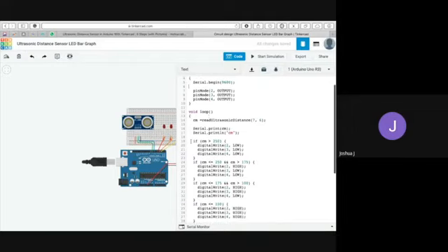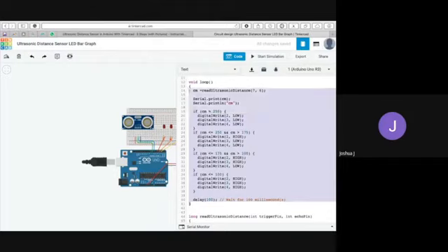And this is my main loop. In my main loop, I call a function. This is my own function that we write for our custom use, and here we read the value. When line statement 14 is executed, it will go to this function, and the function's statements will be executed. What this function does is, first, set the trigger pin mode as output.